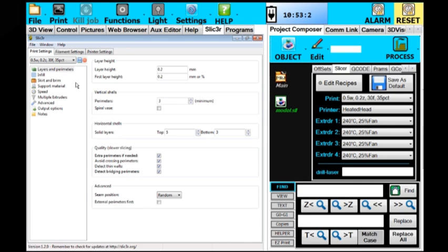Let me start here. This is our default recipe, and what this means is it's a 0.5 millimeter path width for the 0.5 millimeter nozzle. It's 0.2 millimeters or 200 microns in the Z each layer. My feed rate is 30 millimeters a second or 1800 millimeters a minute, and I'm going to use a 35% hexagonal or honeycomb infill. And we can look at all these options, and that's just listing the most commonly changed options, but there are many pages of data here.